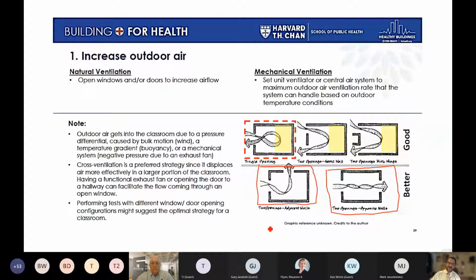the problem is that I've done many, many field studies on this type of situation. And what they're not taking into account is the direction the wind is blowing in that day. If the wind is blowing away from the window in this manner here, you won't get any of those air changes. In fact, it'll just be pulling the heat right out of the room. In fact, because of the second law of thermodynamics, heat will always go from hot to cold. So as soon as you open the window, the heat from the room is going to be going out through heat convection currents. So even though it seems like a simple solution to open the windows, it really isn't, unless it's a controlled amount.